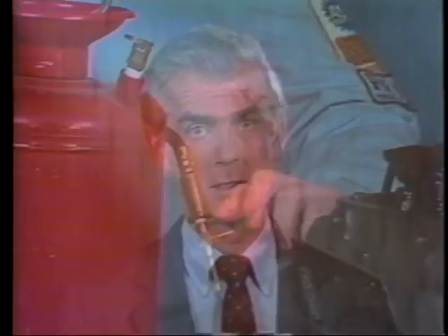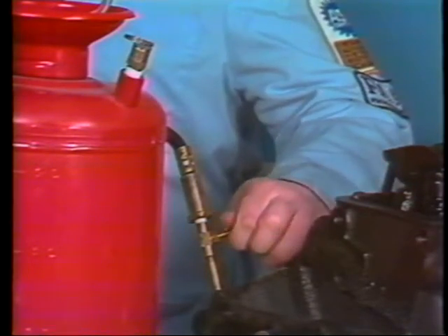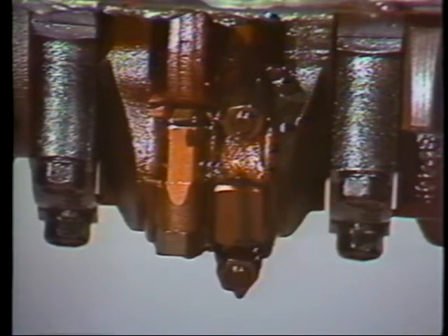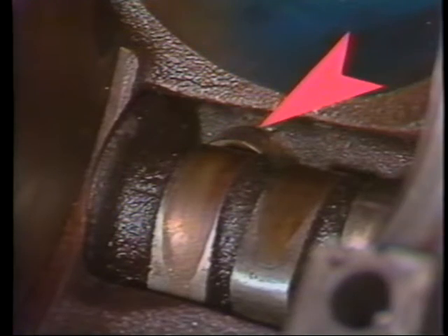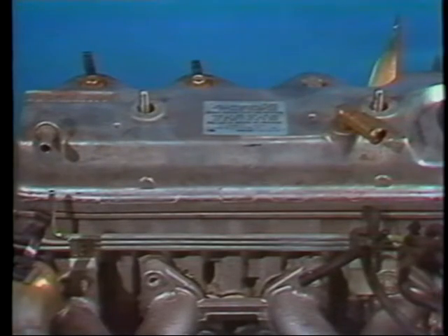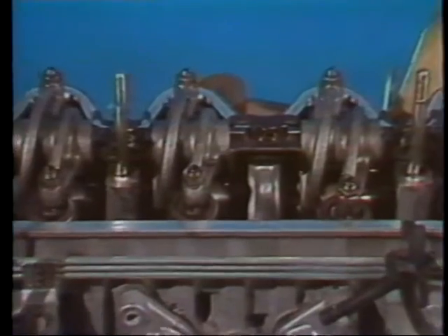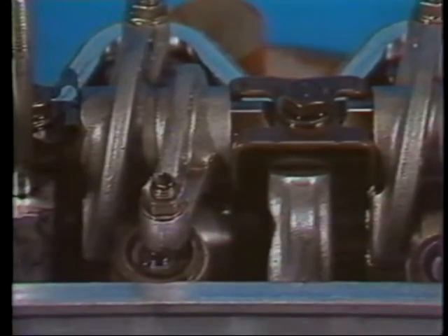When oil pressure is low but there are no engine noises to indicate the problem area and the oil pump checks out okay, the equipment shown can pinpoint the source of the pressure loss. By connecting pressurized oil to an oil galley, you can see where there is excessive oil flow. Pay close attention to the rod and main bearings, the camshaft bearings, and the lifter bores. If the rocker arm shafts are pressurized, remove the valve covers and view the rocker arm shafts for leakage. This procedure will also help locate a crack in one of the oil galleys in the block.